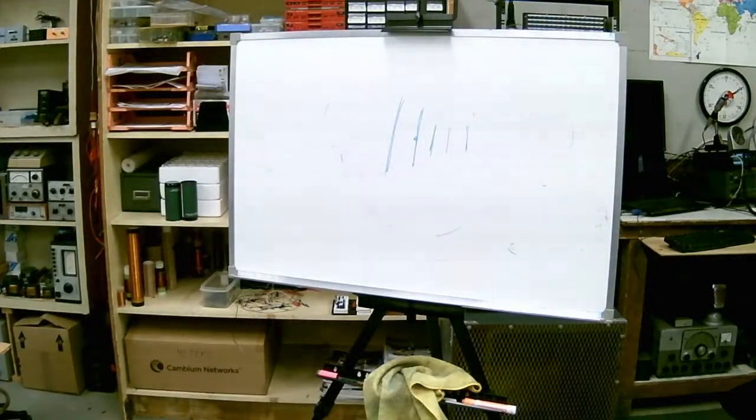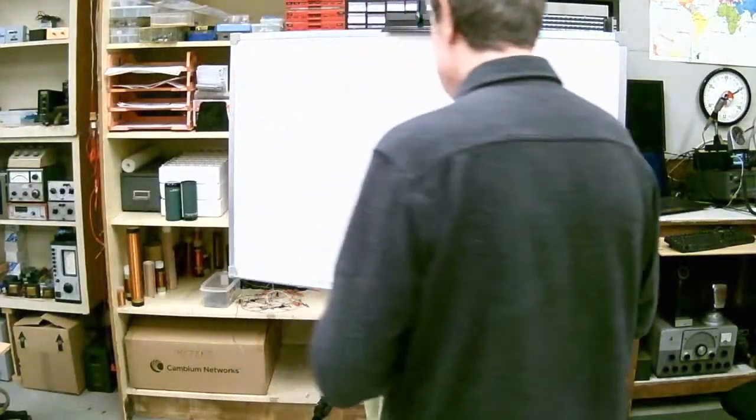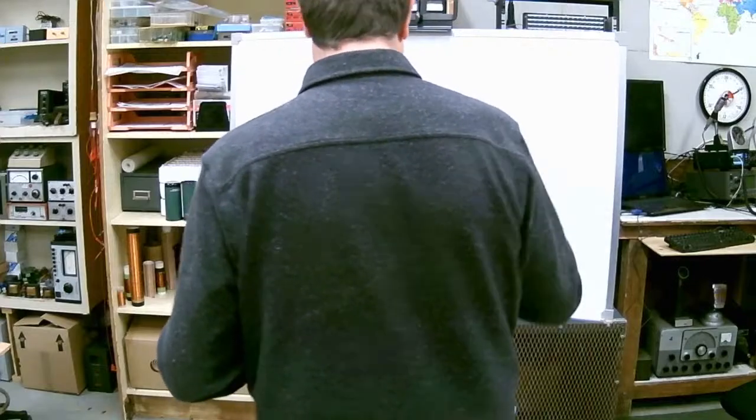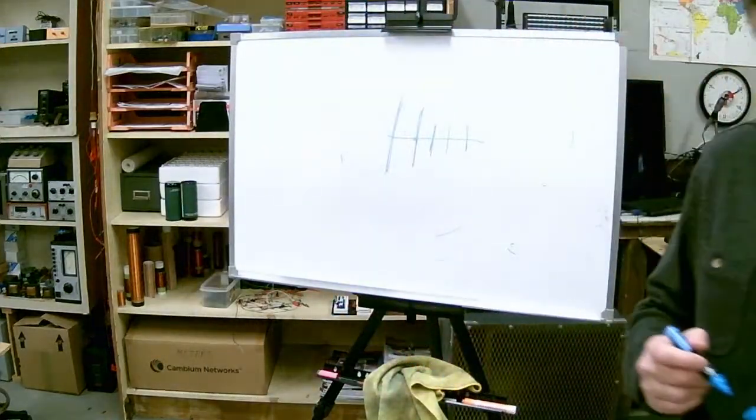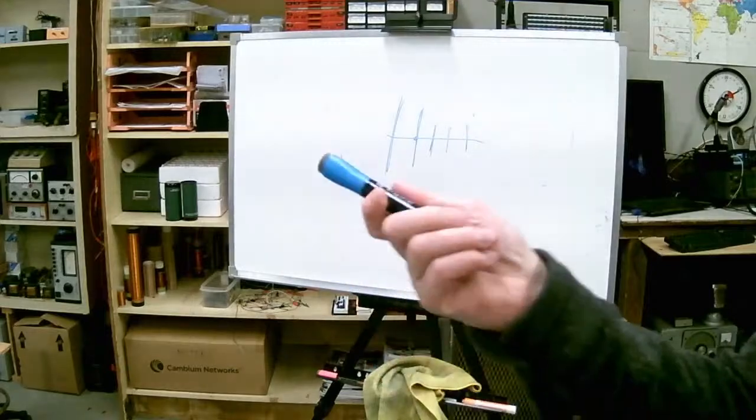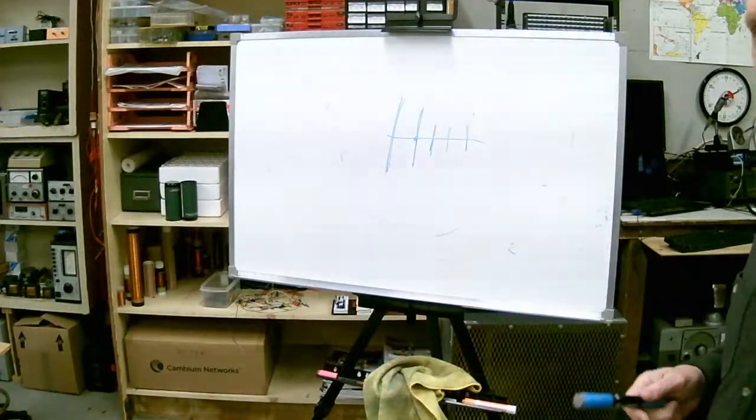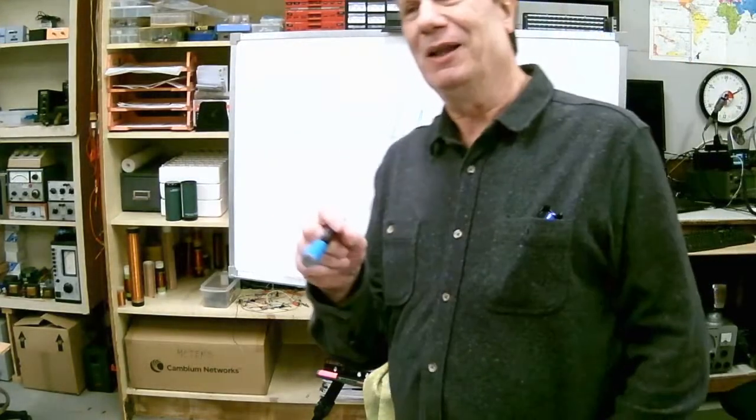A folded dipole has 4 times the impedance of a standard dipole. So it's about 300 ohms, 72 times 4. Anyway, this is how your high gain antennas are designed, by careful tuning and applying it. I've got that modeling program that will optimize that kind of stuff. So you did a little bit better, the higher.